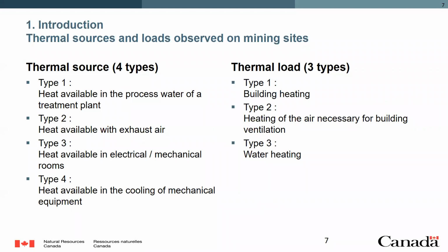Okay. On the load side, once you capture this heat, where can you put it? Basically, you can use it for building heating, or you can use it for ventilation heating requirements, or for water heating. Okay. Just in simple terms, think about preheating. So you take the energy of what you're dumping into the environment, and you use that for preheating the liquid or the gas that is going into another process. That way you can save the energy, basically.